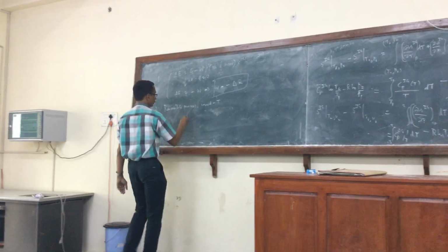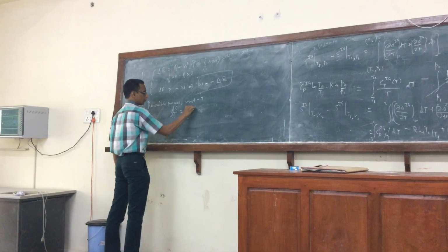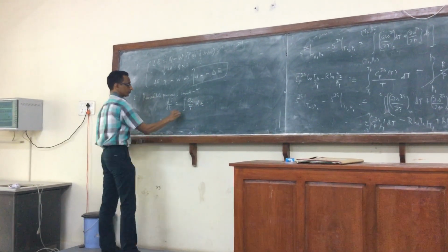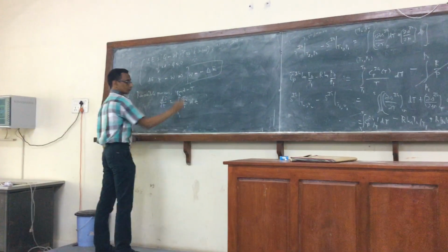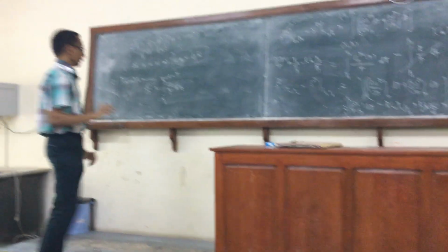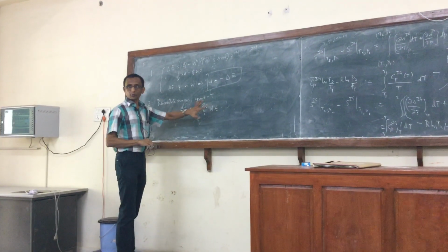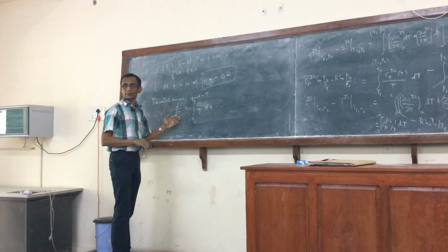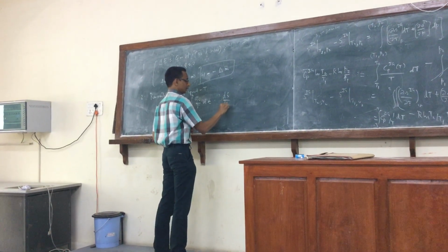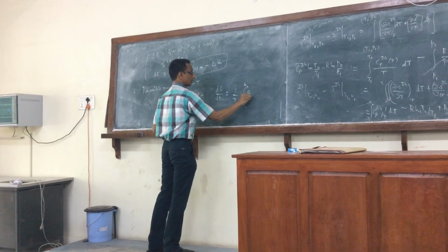So now we know that dS equals dQ by T for a reversible process, equality holds. This is a very general way of writing it. And later we brought in the temperature so that you can clearly see how constant temperature will simplify. For constant temperature, delta S is simply 1 over T, integral from 1 to 2 of dQ_R.